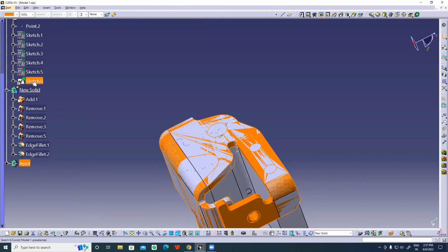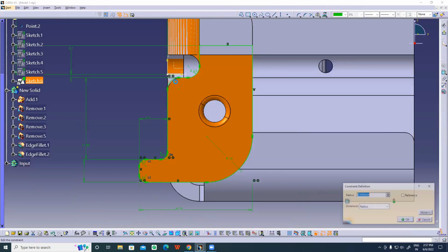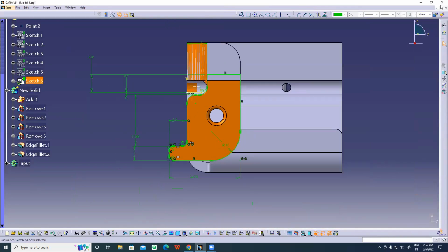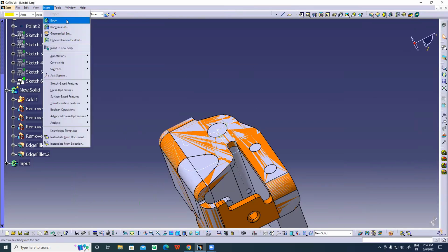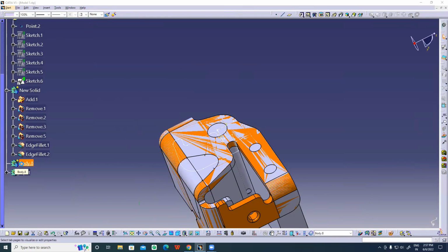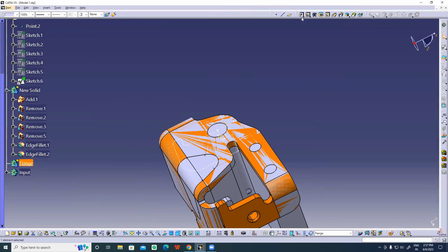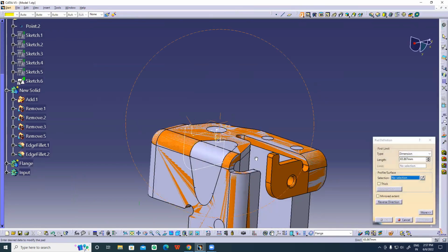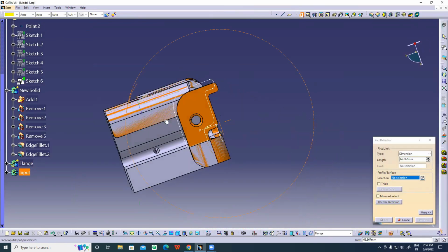Okay, I accidentally exited from the sketch, and select this and exit now. So once after exiting from this, you need to create this new body. Insert a body, and you can name this something like flange. It's a kind of extension, right? Flange. Everything is appropriate naming. Okay, you don't need to give the exact name and all. You can give an appropriate name and pad it.